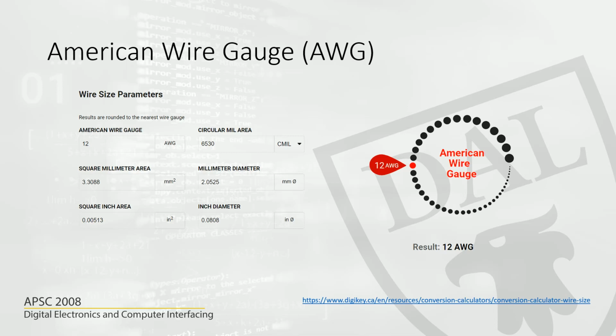But again, when you purchase all these, you will have to make sure that the voltage doesn't drop too much. You would generally observe that if a power bar has a longer cord, say a 30 meter extension cord, the wires are going to be bigger in terms of diameter. It's because bigger wires have lower resistance, right?